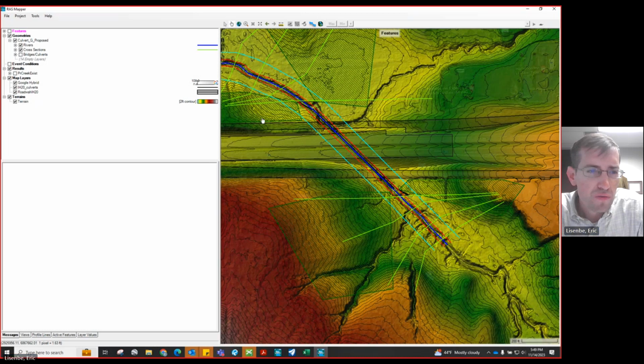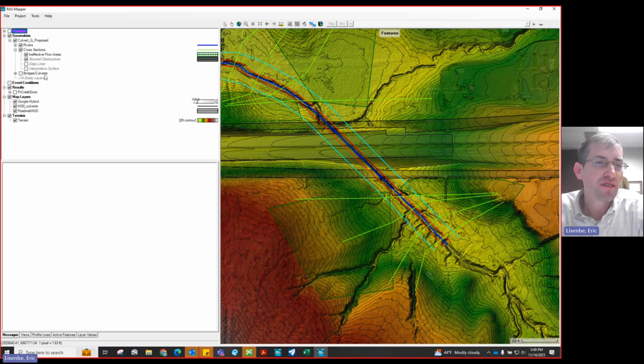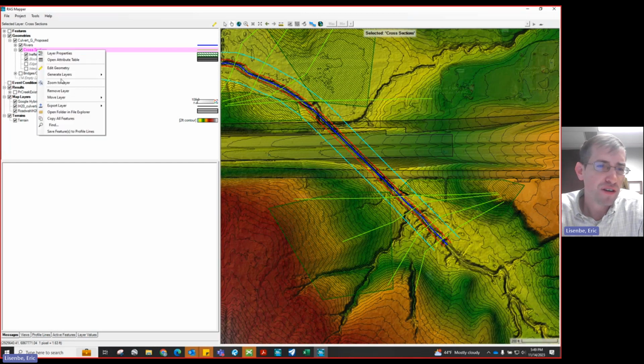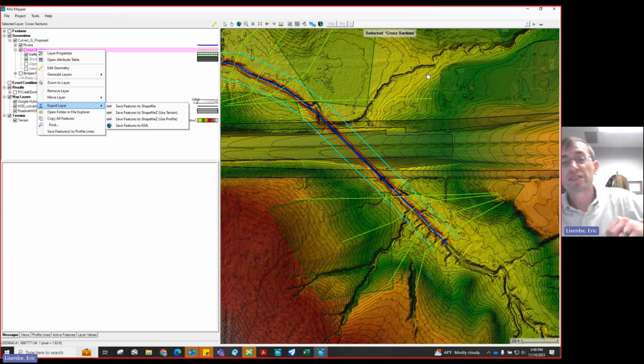One of the things I've done, our roadway design is in Open Roads Designer. So I will just show you the process. I took these cross sections out of our model, exported them to a shape file, and then brought them into the DGN file we have in Open Roads, applied the correct scale factor to get it lining up with everything we have in the design. So that's just a few little nuggets before getting started. And now we'll go ahead and show you